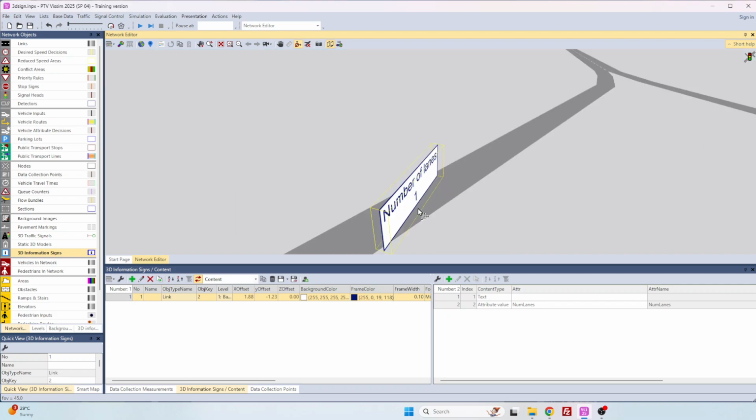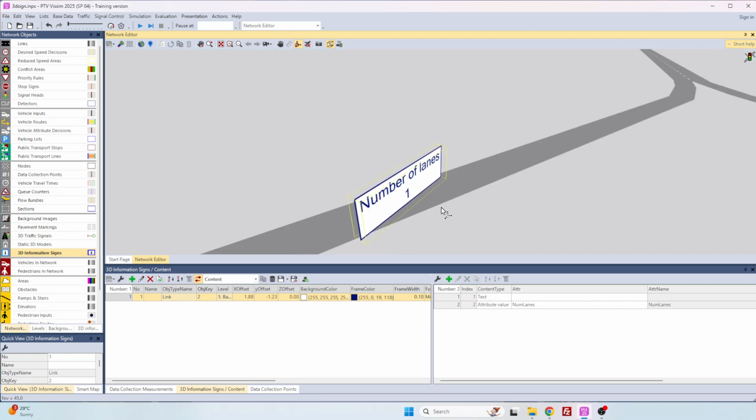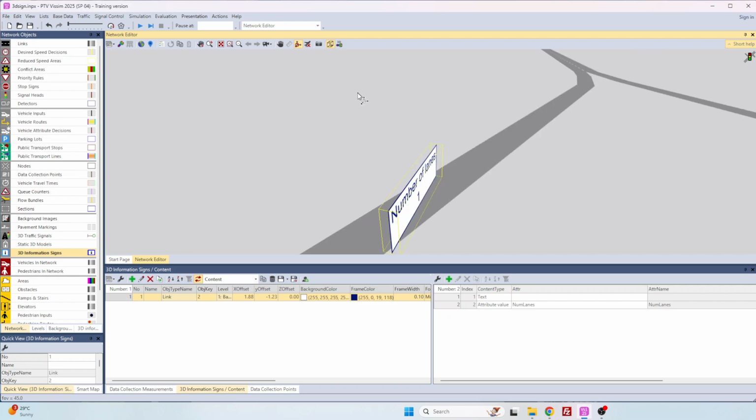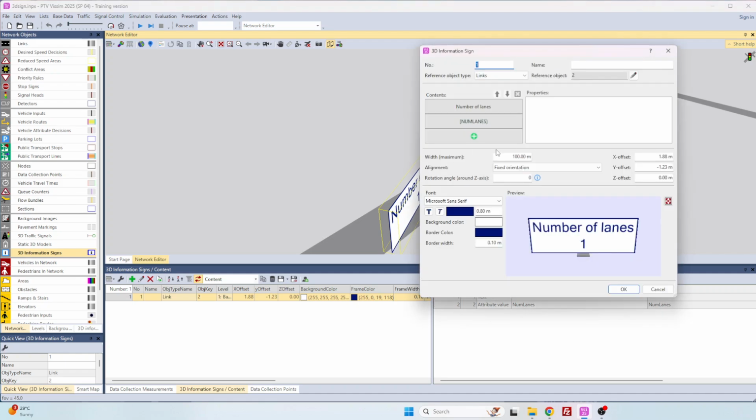it has not a good rotation, so it's hard to see. If you untick these, you can select it here in 3D view. If you have this selected, you can't select or open the dialog box. But if you untick these, you can double click on it and it will bring up this window. You can put rotation to camera.